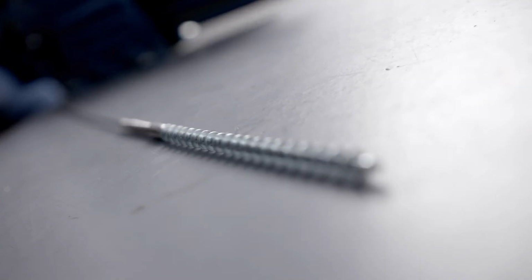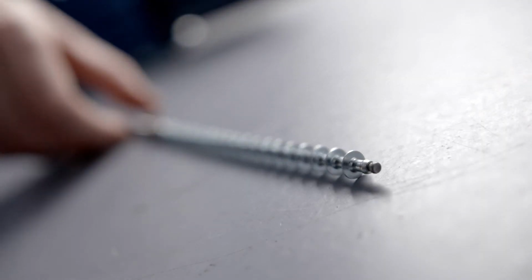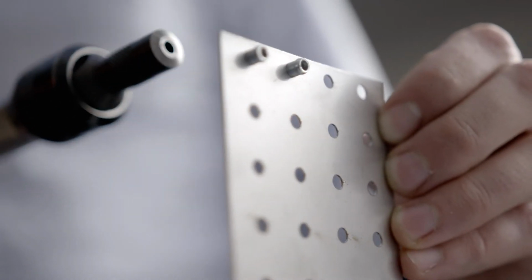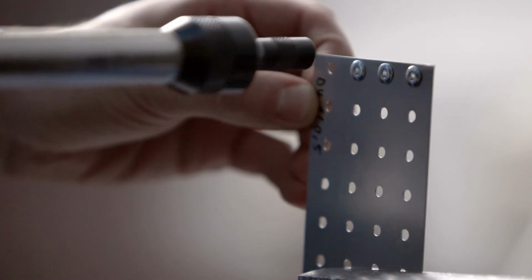Speed rivets are used in applications where manufacturing speed is required and we don't have high requirements in regards to tensile and shear forces within the application. The big advantage of speed rivets against normal blind rivets is that you don't have to reload the installation gun every time you want to install a blind rivet.